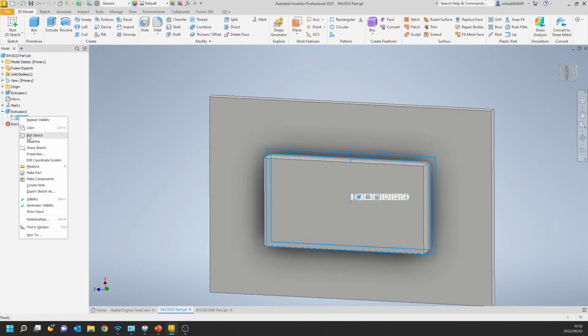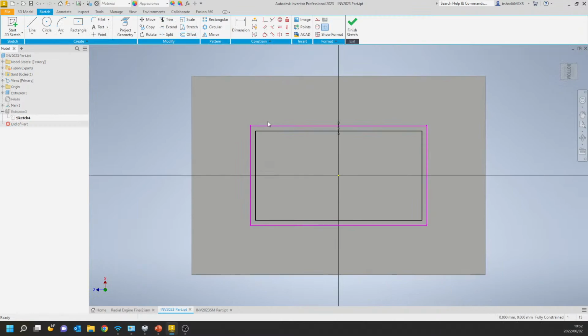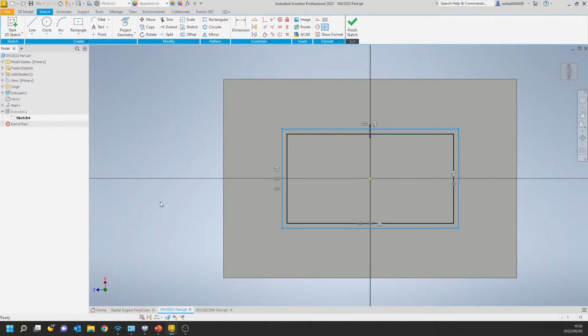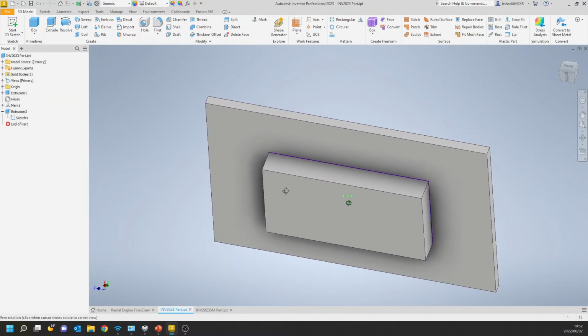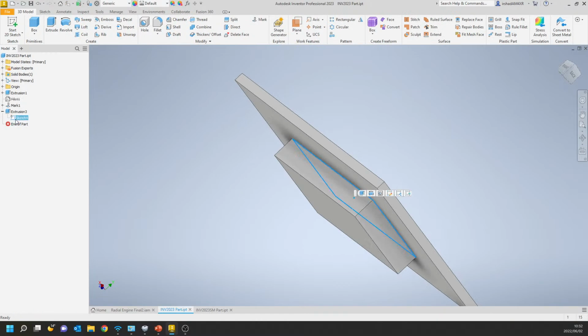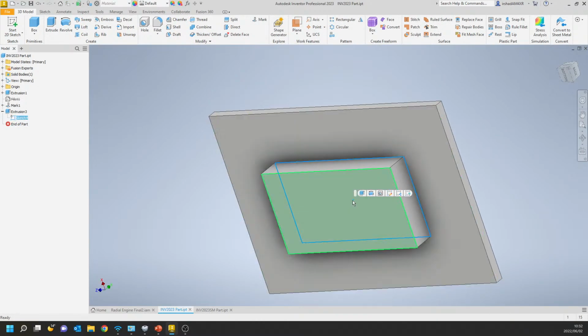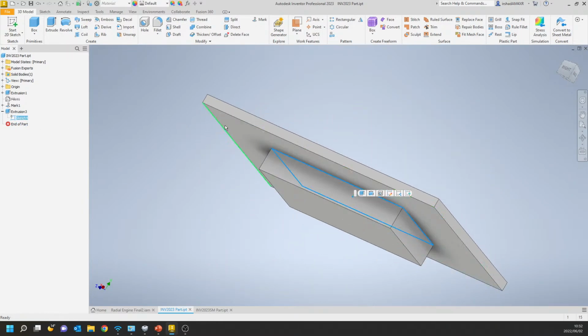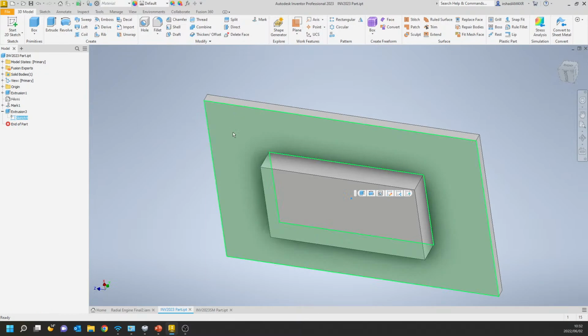So the new tool is that I can go in when I'm editing the sketch. To fix this, I would have had to select each of these lines or do something with it. But right now you can simply click anywhere in the blank space and select broken projections. That will highlight everything in the magenta color and ask what would you like to do with it. I can simply delete it and get rid of it completely without much hassle. Of course, that passes the problem onto the next set of lines, but that's just in this particular case.